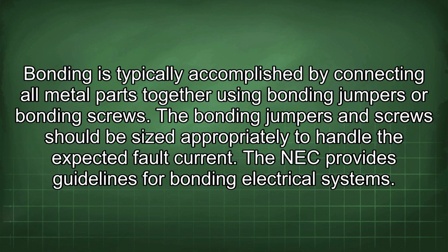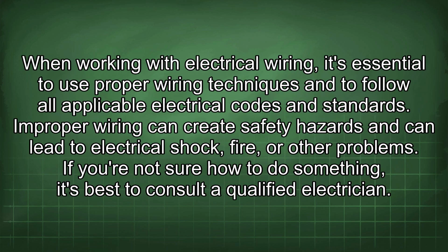The bonding jumpers and screws should be sized appropriately to handle the expected fault current. The NEC provides guidelines for bonding electrical systems. When working with electrical wiring, it's essential to use proper wiring techniques and to follow all applicable electrical codes and standards. Improper wiring can create safety hazards and can lead to electrical shock, fire, or other problems.